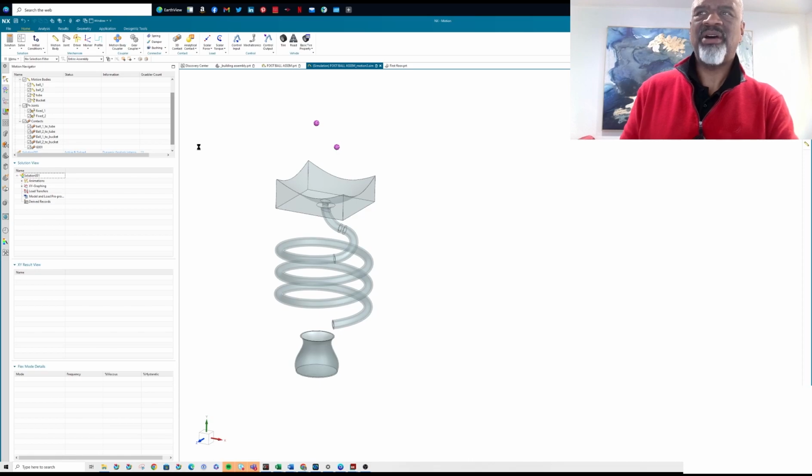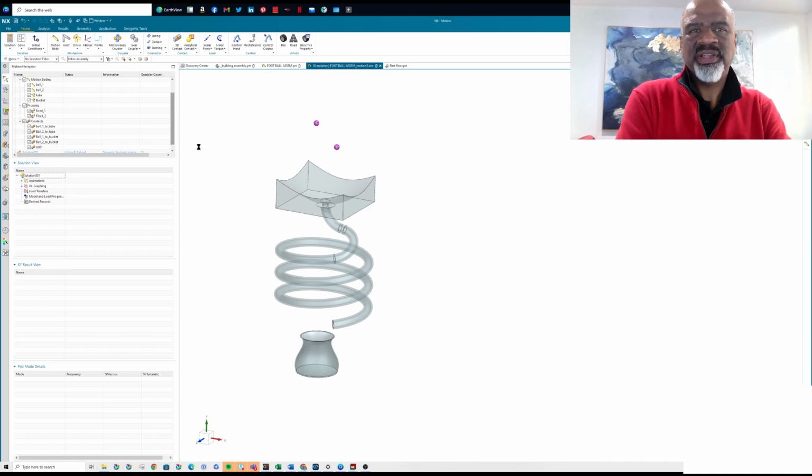It's an incredibly powerful tool that allows you to truly calculate what happens when real things contact each other. It has the friction, it has the good way of figuring out what happens when they meet. The animation in this program is really great, but it's not a simulation. It doesn't take all of this into account. And it's important to do the mass properties. As you may recall, when I did the mass properties of the rigid bodies and the balls, I was just able to click on that little button that automatically calculates it for you.